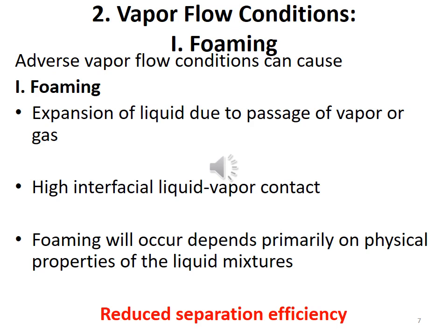The process of foaming depends primarily on physical properties of the liquid mixture, but it also sometimes depends upon the design and condition. Whatever the cause of the foaming, this foaming process can reduce the separation efficiency of the distillation column.